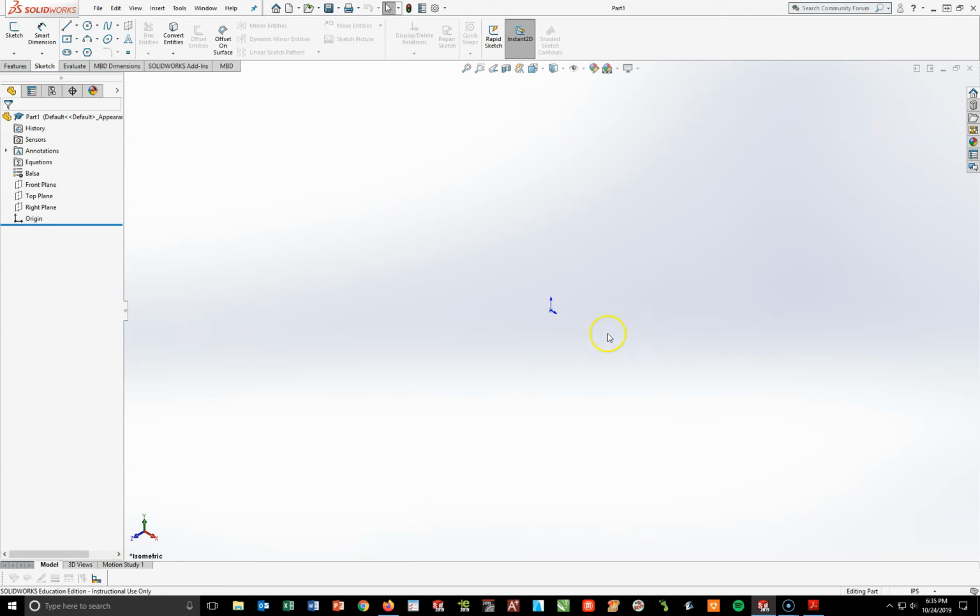Okay, so in this case, this is a really important point to SOLIDWORKS. Everything we do in SOLIDWORKS has to relate to this origin. So it's really important that as we start to design stuff, we have some kind of relationship to this origin, whether it's through a dimension or that we are drawing directly on top of that origin. SOLIDWORKS will get easily confused or give you error statements if you don't have your part or your design related to this origin. So as we begin to do our drawing, you're going to hear me reference this origin quite frequently. So pay attention to that.